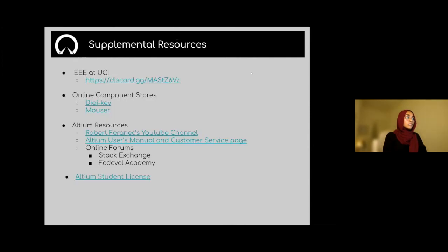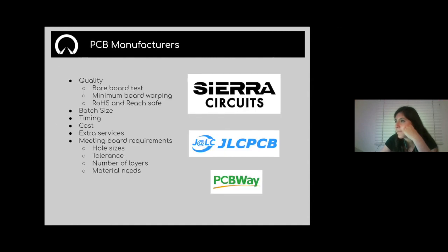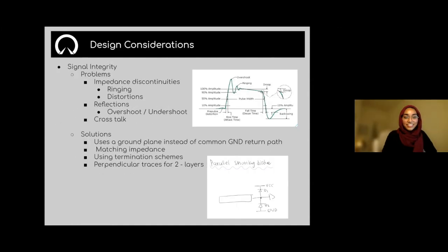Oh yeah, for sure. So Safia, could you go to the right tab? Just keep on going back until we go to the signal integrity one. There you go. Okay, so essentially, when you have reflections, that just means that this entire signal isn't going through. So that means that there's just this excess voltage that's going from the source to that point back and forth until it dissipates as heat.